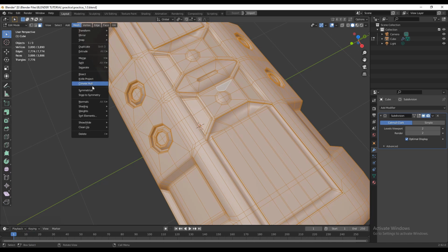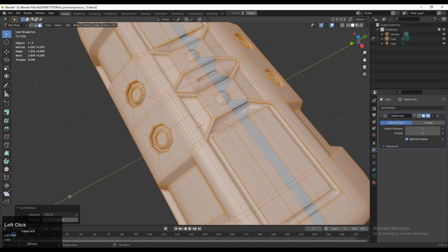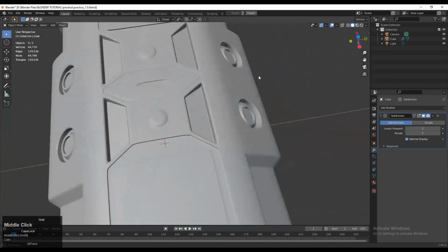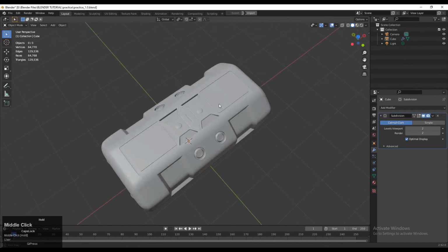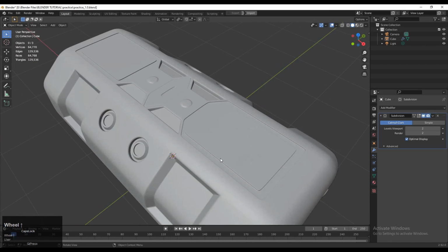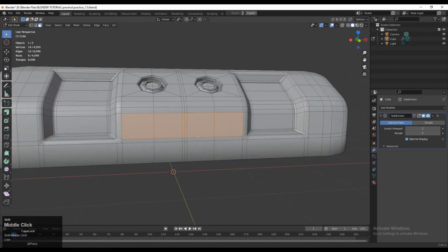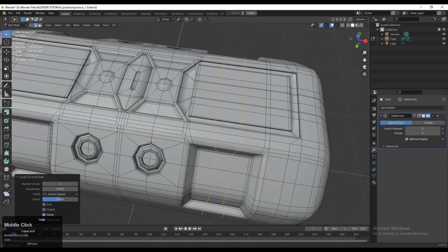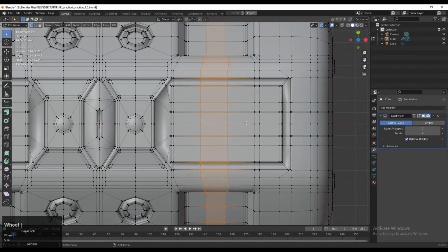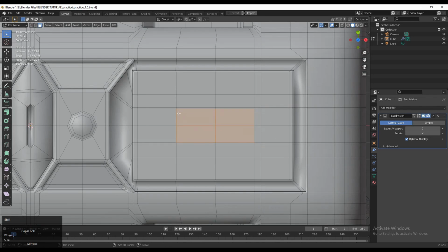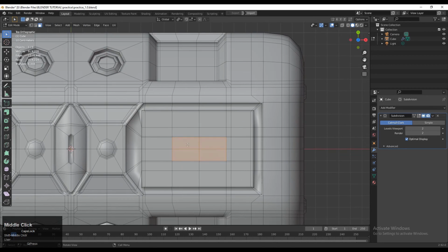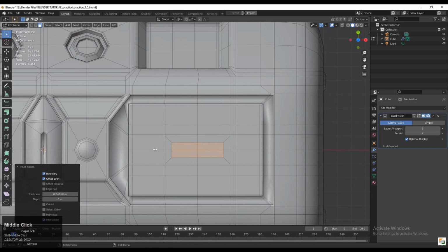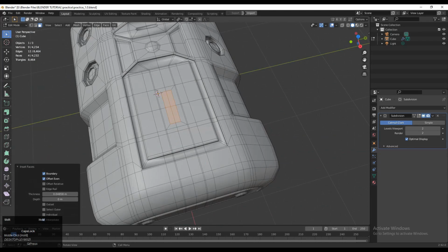So this is the Subd hard surface modeling. You need to work on its topology more. That's the thing. And now we got a decent look for the model and we have solved that boolean problem. Now I want to create a little bit of design on it, and with Subd modeling it's easy to create a little bit of design. You can select a few faces and move them here and there, and then you will get that kind of design. So these things also happen.